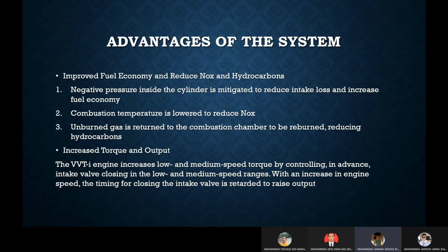And now we go into the advantages of the system. The first point is improved fuel economy and reduced NOx and hydrocarbons. The negative pressure inside the cylinder is mitigated, reducing intake loss and increasing fuel economy. Second, the combustion temperature is lowered to reduce NOx. Third, unburned gas is returned to the combustion chamber to be reburned, reducing hydrocarbons and emissions.